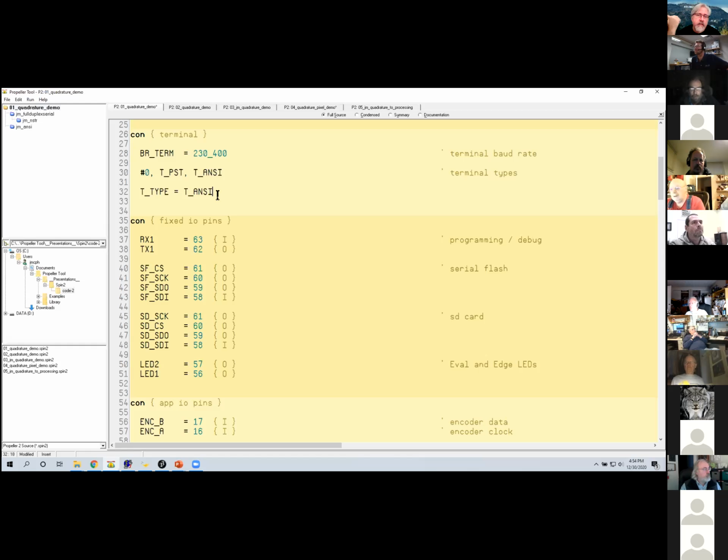The other thing too is in that particular product, I wanted to have a 1 millisecond timer that I could use for timing and other things. We don't have a getms in the P1 like we have in the P2, so I had to synthesize it. I created an extra variable, and in that loop, I would grab the counter at the beginning of my code within the loop, and grab it at the end, and then print that out on my screen. I just kept adding code to my background loop until I didn't have any more space. It is shocking, even in the P1, how much Spin code you can run in a single millisecond. So I sometimes do that.